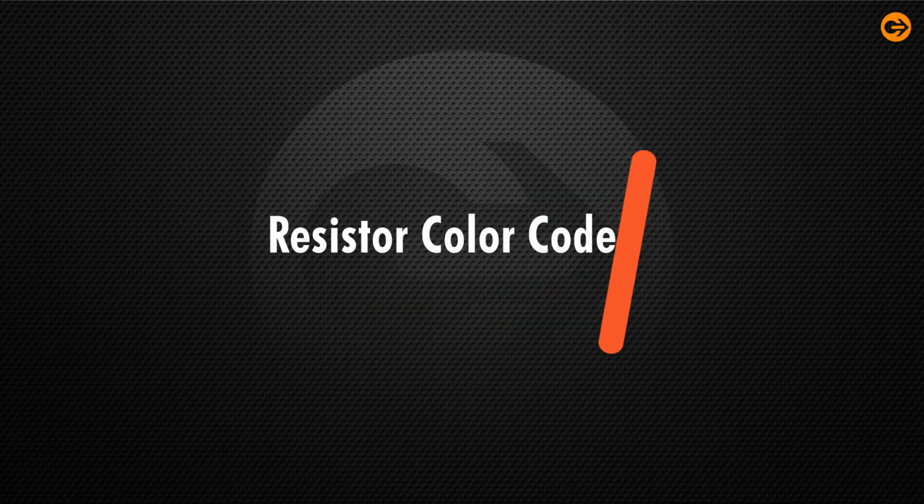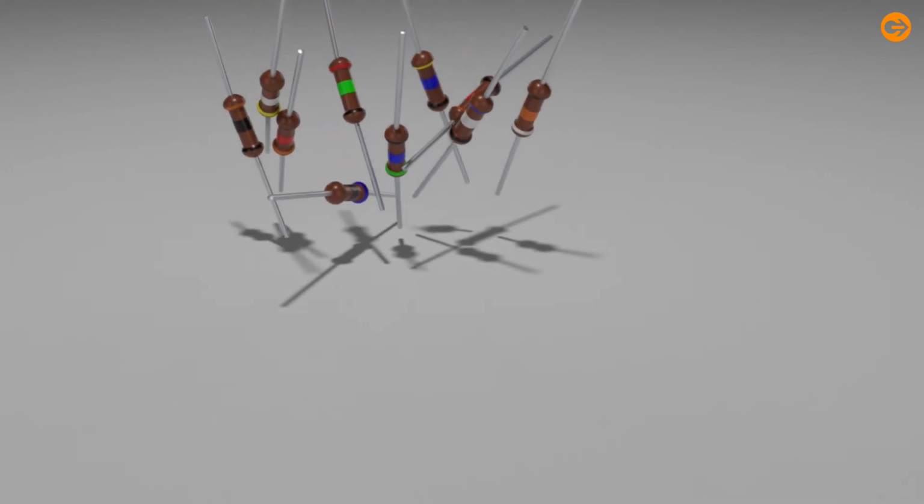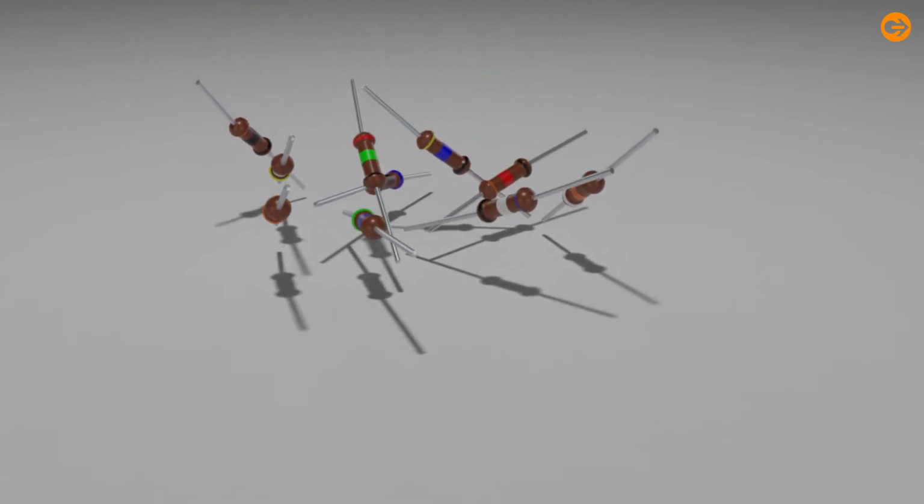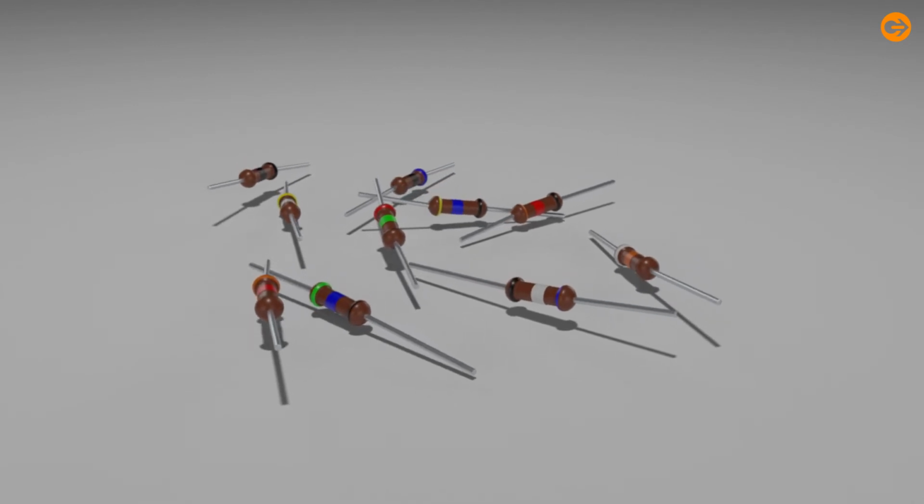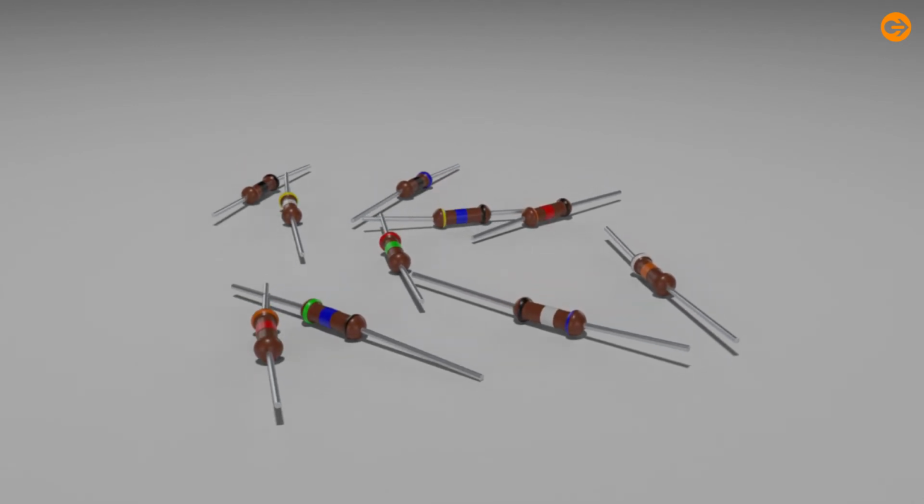Students, there are resistor color codes which you must fathom. There are different types of resistors which can be used in both electrical and electronic circuits to control the flow of current or to produce a voltage drop in different ways, right? But any random resistor cannot be used everywhere, right? Therefore, they are available in a range of different resistance values from a fraction of an ohm to millions of ohms. It would be impractical to have every possible value, for example 1 ohm, 2 ohm, 3 ohm, 4 ohm, etc., because millions of different resistors would need to exist to cover all the possible values.